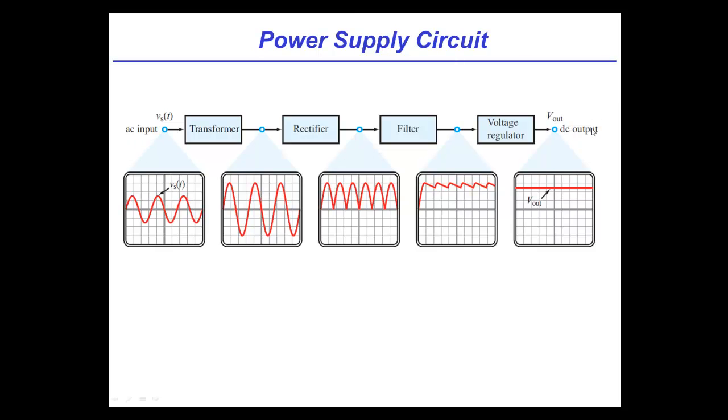Well, I think there's various things. One is the AC in the mains, depending on where in the world you live, might be 110 volts, might be 220. That voltage is much higher than a typical electronic circuit would need. So first thing, we're probably going to reduce the voltage somehow. And then we got to find a way to convert it to DC. That's right. And then the final thing is, I've heard that a lot of these electronic circuits want pretty stable power supplies. Right. They don't want the DC to be varying or have any noise on it. So we got to do something to get a nice steady DC signal.